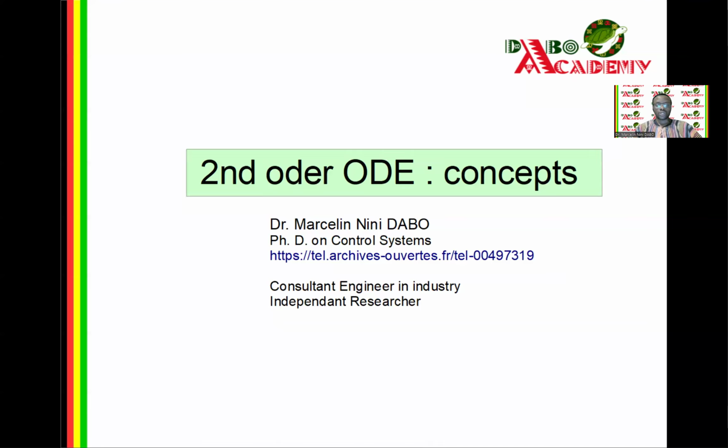I also talk about a formula that I called an ISO time constant formula because it allows you to compute according to the time response at any fixed percentage of the output during the transient or at any rise or fall time during the transient also, the time constant.